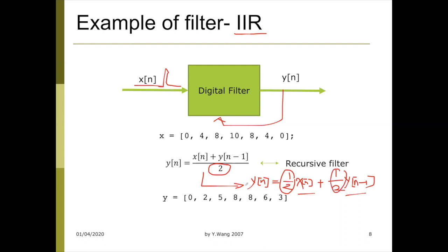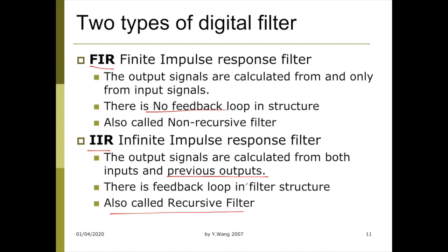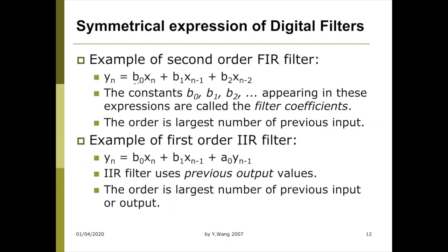Okay, so to look at this, we can understand the general form of the expression. We have coefficients with the input signal, the previous input signal, and two previous signals. This represents a typical FIR filter. This FIR filter has 3 coefficients: B0, B1, and B2. If the filter has been designed already, that means you know the values of B0, B1, B2.